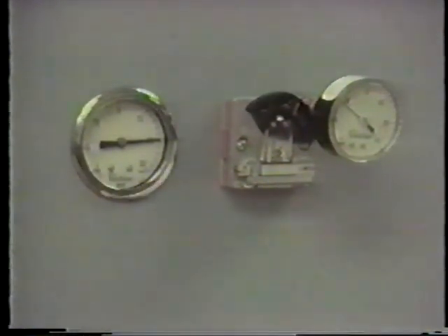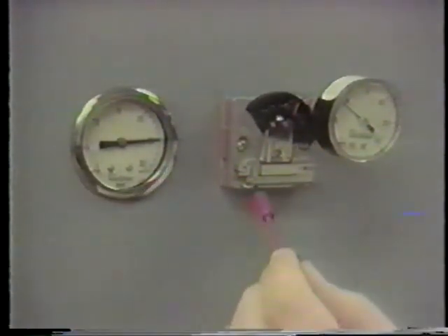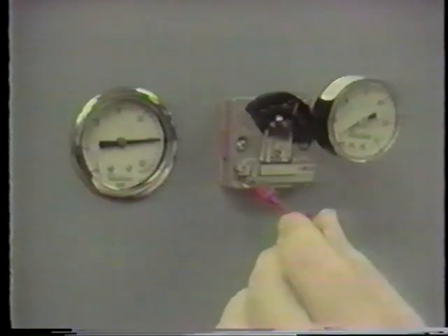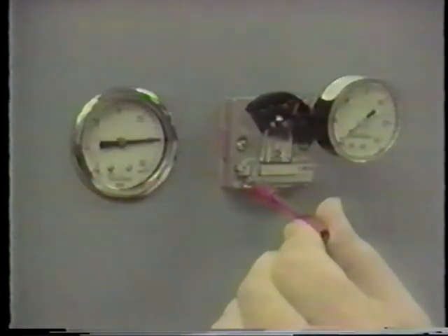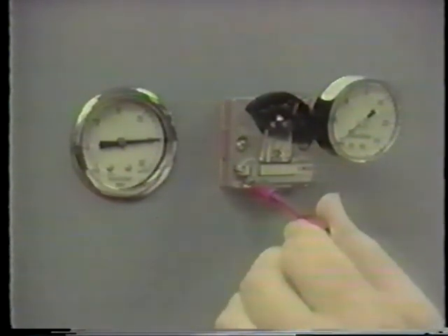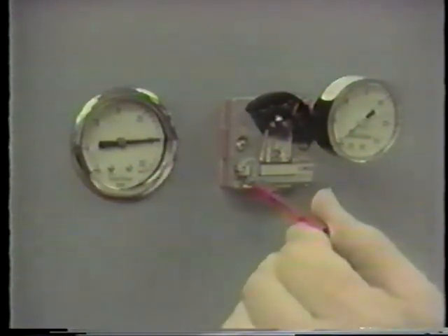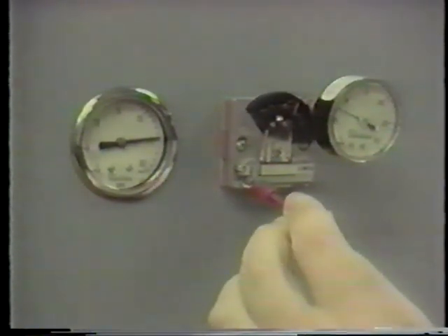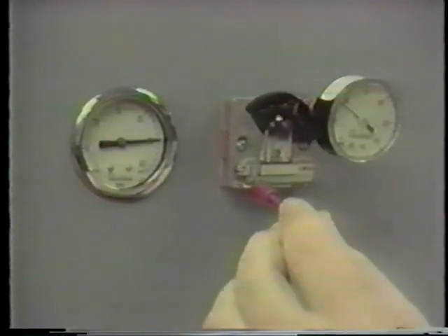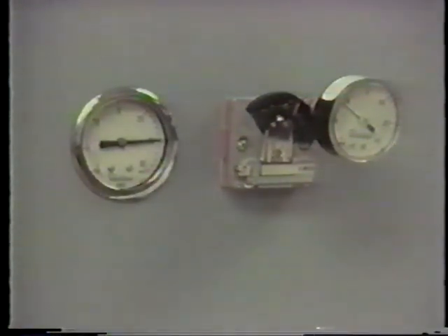If it does not read correctly, it can be adjusted by turning the calibration screw either clockwise to increase the reading or counterclockwise to decrease the reading until the dial rests on the stop. Continue rotating the screw in the scale a small amount, then turn the screw back to read 9 psig and check the scale. It should read ambient temperature within 1 degree Fahrenheit. It may take more than one try to accomplish this calibration.